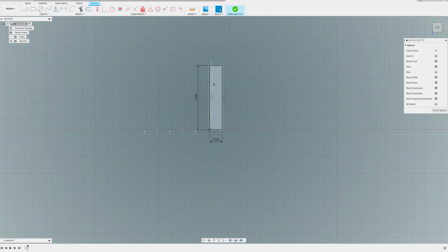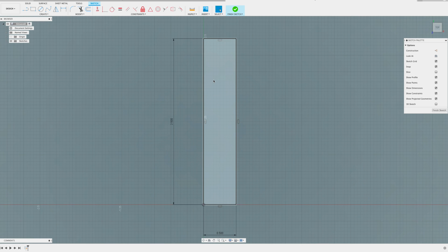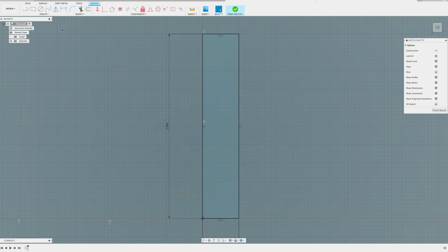Okay, and now that we have this, we're going to draw the design for half of a bullet. This time I do want you to draw the projectile just the same way that I'm doing it. So I'm going to start with the spline tool here at the top. I'm just going to pick a few points and make a round nose like that. And remember, before you click again, you just push enter to say you're done with the spline. Otherwise, it kind of keeps drawing.